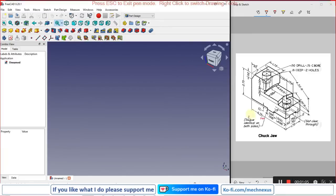Now we will read our model and how we are going to model this. First we will make a solid extrusion of the outer boundary, like this, of 1.75 inch symmetric to the plane, and then we will add these chamfers, this cut here, and the cut at the bottom portion, and then at the end we will add this hole. So this is how we are going to model this part. So let's start.